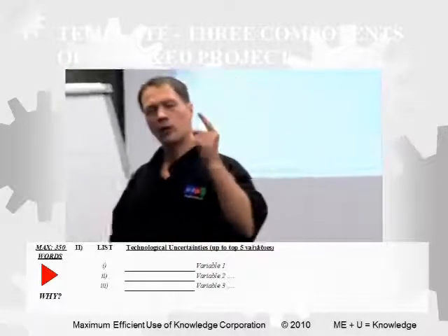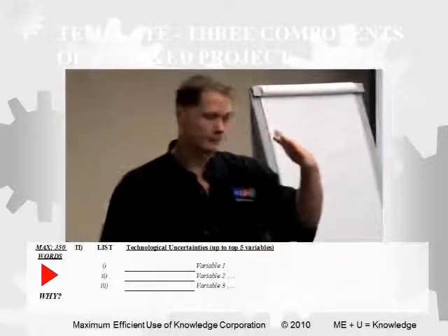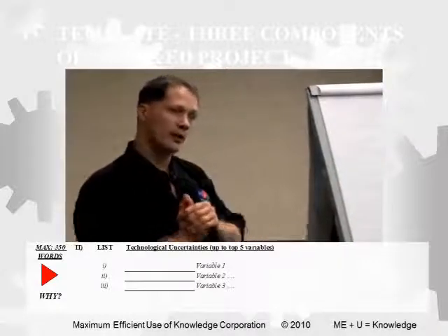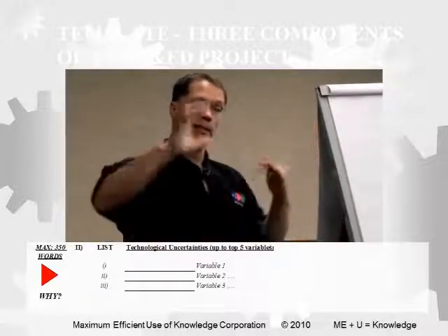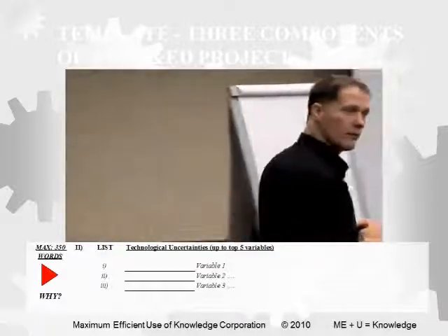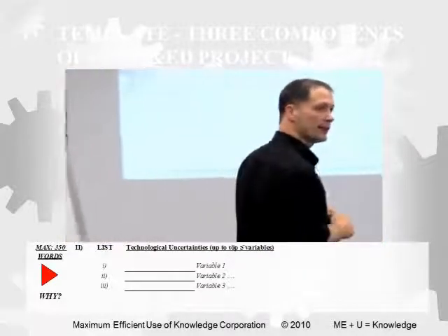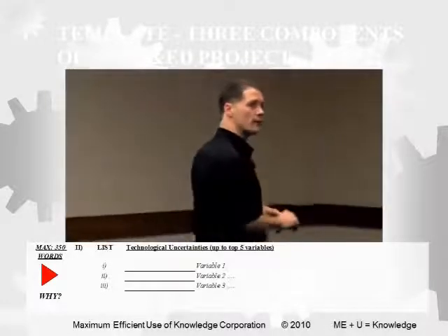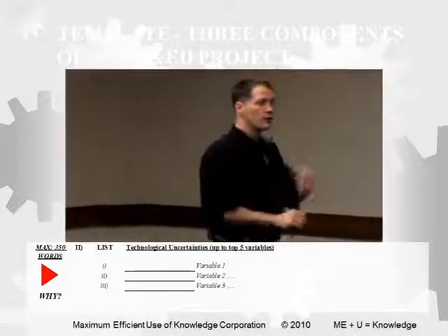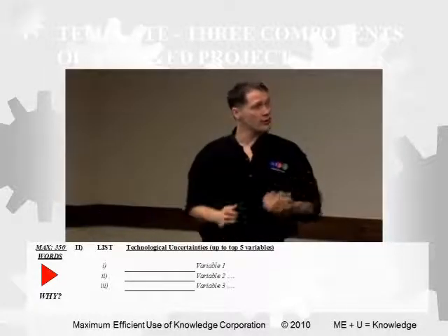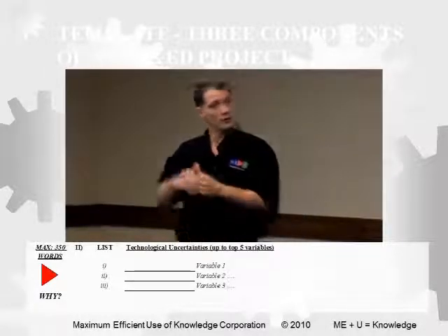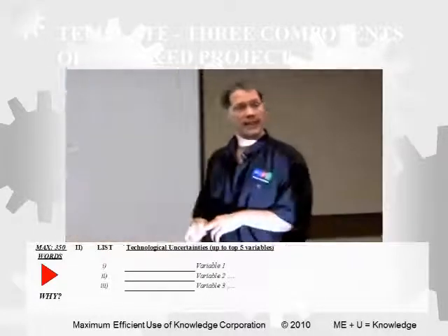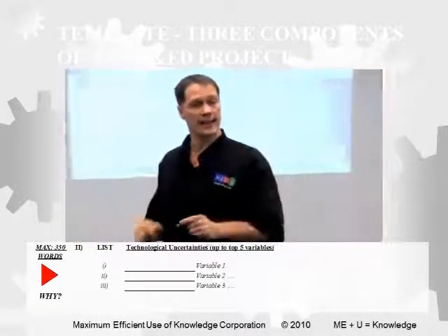If instead I say, well, you know what, I got to do 10 tests for temperature and 10 tests for pressure. But if I can argue, if I vary the temperature, then the optimal pressure would vary. How many people think I have 20 tests in my design of experiment matrix? How many people think I might have 100 tests? For each of the 10 temperature tests, I have to test pressure 10 times. So technically, I have 100. So if I add a third variable, like the amount of glass fiber in the mix, another 10 tests, now I have potentially 1,000 tests in that matrix.